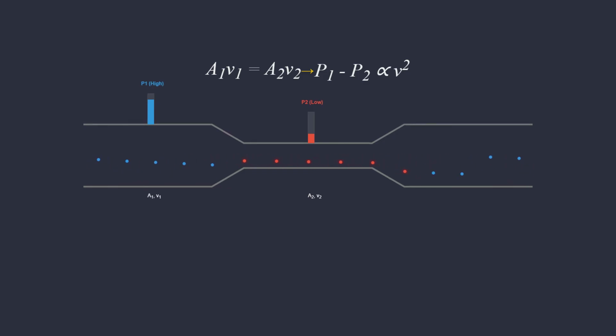When a fluid flows through a converging section, known as a throat, the cross-sectional area A decreases. The continuity equation, A1 V1 = A2 V2, mandates that the flow velocity V must increase proportionately to the area reduction. This mandated velocity increase necessitates a corresponding decrease in static pressure exactly as predicted by Bernoulli's equation.